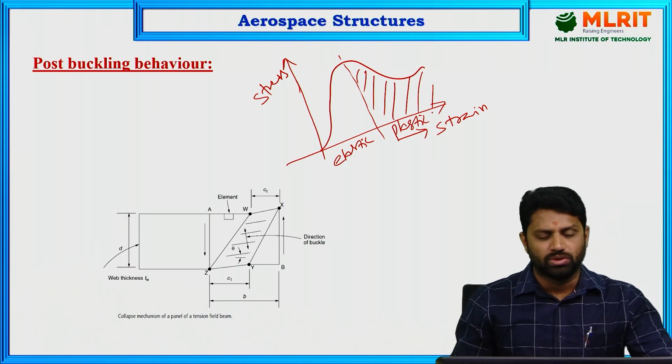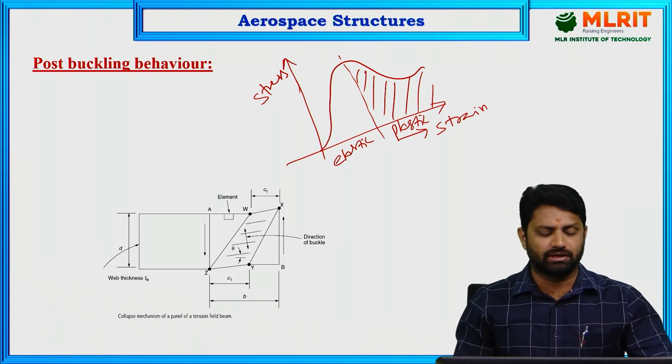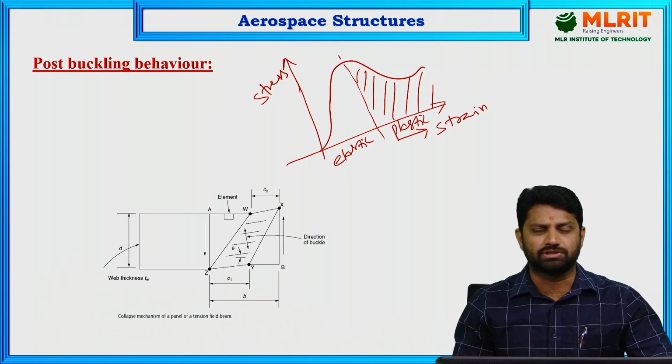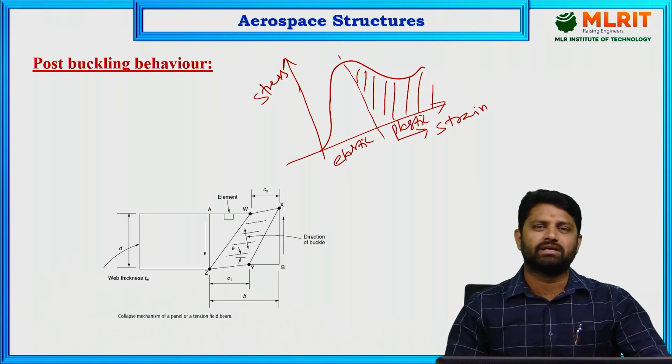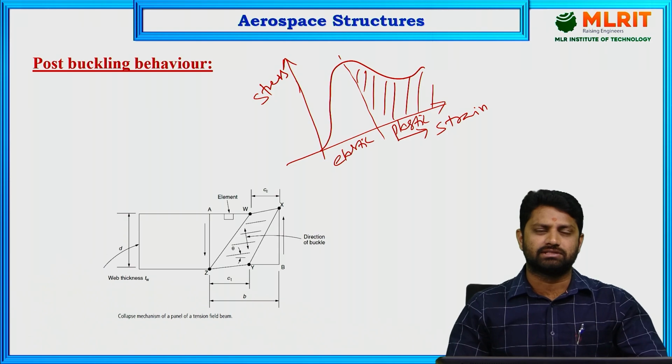So the calculation of the parameters is going to be much more difficult, and usually not linear, because it is a non-linear analysis that we are going to study here. Therefore the post buckling behavior is very important for every engineer to understand, because we study up to the buckling process, but after buckling, what is happening to the material, is it safe to add some more loads to it, and if it is safe, how far can it sustain the loads that we apply after buckling has occurred.